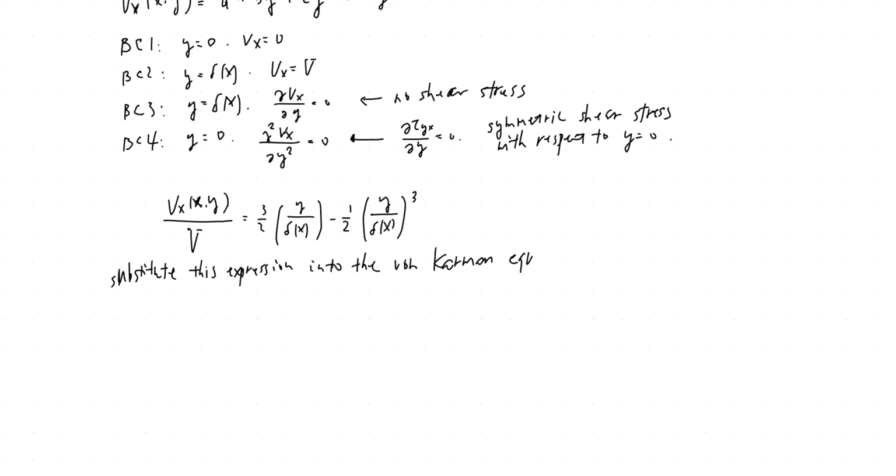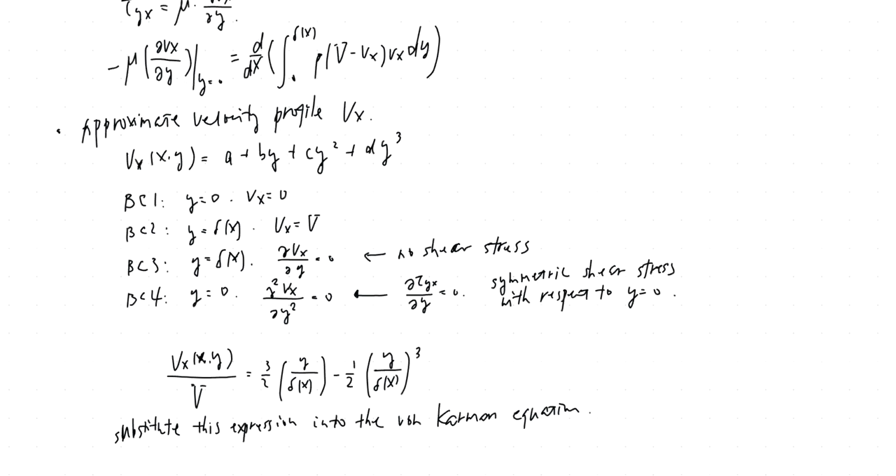Now let's see, why do we do this? Here, we approximate the velocity profile by assuming it's a cubic in y, or a polynomial function in y. And then we solve this totally by using the boundary conditions. And you may feel it's so strange. We use the conservation of mass and conservation of momentum, we derived so many equations, but now we are only assuming a profile.